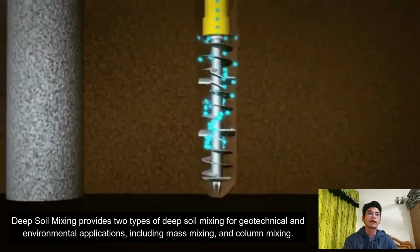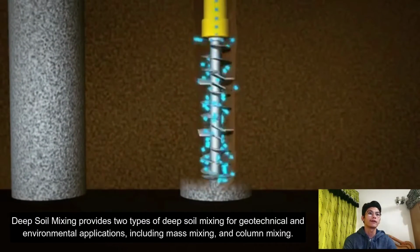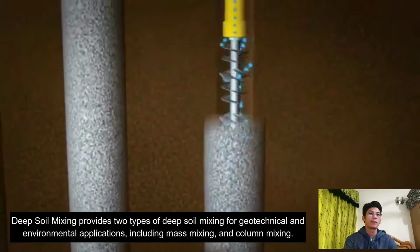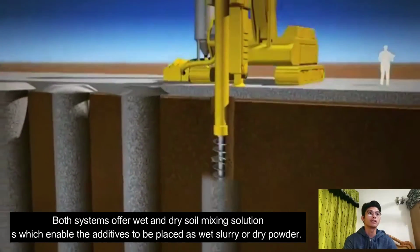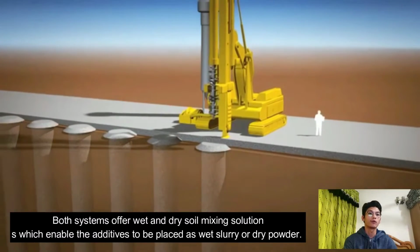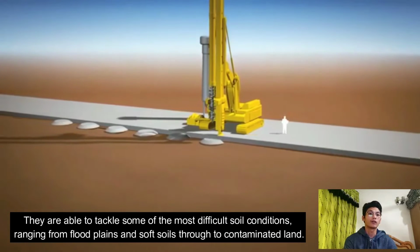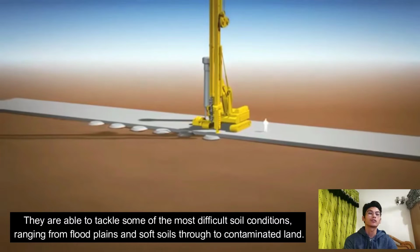Deep soil mixing provides two types of deep soil mixing for geotechnical and environmental applications, including mass mixing and column mixing. Both systems offer wet and dry soil mixing solutions, which enable the additive to be placed as wet slurry or dry powder. They are able to tackle some of the most difficult soil conditions, ranging from peat plains and soft soil through to contaminated land.